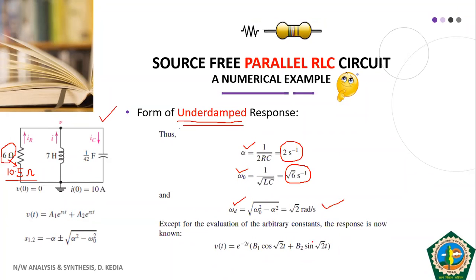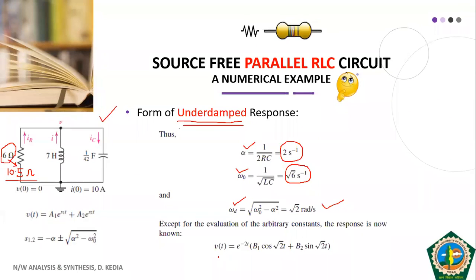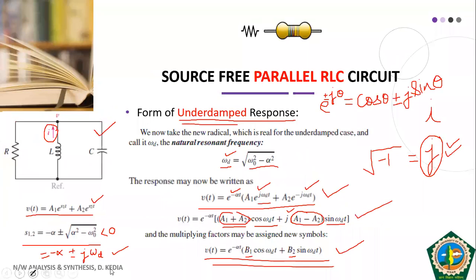Okay, and as we had seen in the previous slide, this was the governing equation of the natural response for underdamped response. So here we substitute the value of omega d as under the root 2 in this equation, and this is the equation for this circuit. Otherwise, for the case of your underdamped response, this is the equation that you have to memorize, where B1 is A1 plus A2 and your B2 is j times A1 minus A2.